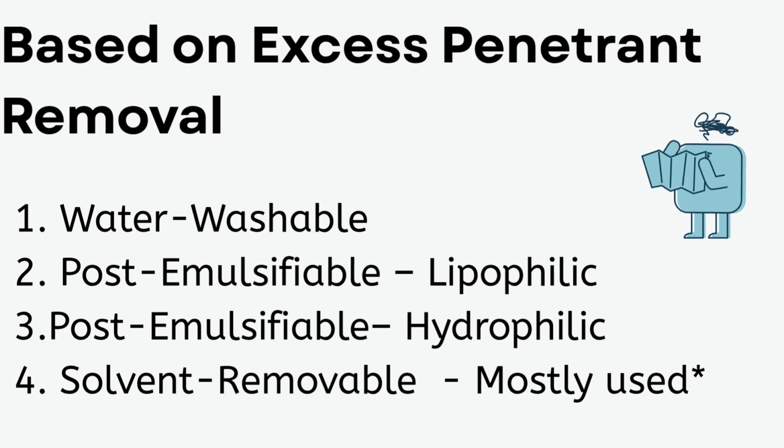3. Post-emulsifiable, hydrophilic. Similar to type 2, but the emulsifier is water-based instead of oil-based. More sensitive and gives better results for fine cracks. Common in aerospace and high-precision inspection.